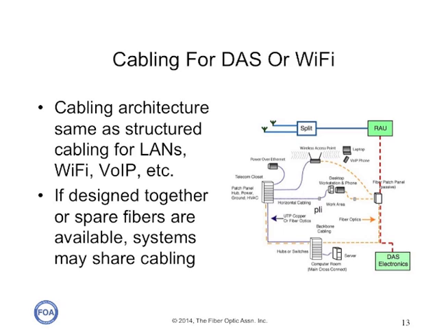Cabling for DAS is very similar to premises cabling networks used for other systems. The architecture of DAS cabling is no different from an Ethernet LAN or standardized structured cabling. A DAS can share backbone cables and telecom rooms where power is available for the remote antenna units. In some cases, DAS can be monitored by the same network management software used for LANs.